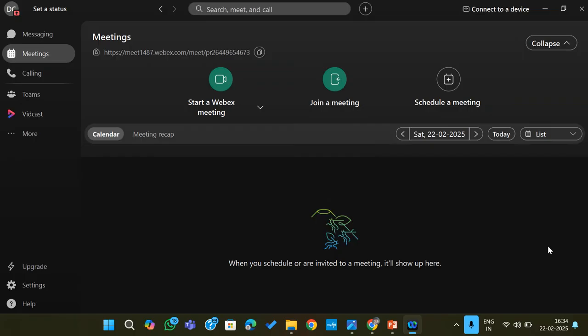Yes, in friction stir welding, there will be a rotating tool which will be inserted into the plate. After insertion, it will make a stirring action inside the plate. That is why there is friction and stirring. In rotary friction welding, there is no tool available; both parts make the joint. But in friction stir welding, there will be a tool.